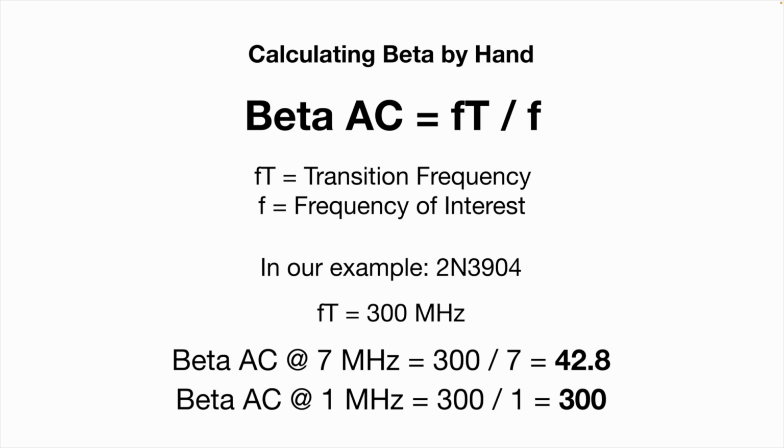All I'm saying is there's more going on, and it is frustrating because I design it on paper, work it all out, model it in LTspice, and think, well, it looks like a different amplifier, none of the figures seem to match. That's because I'm using a small signal model and trying to do some of these calculations by hand. LTspice is doing the same thing, but better, basically, and with access to a lot of other things.